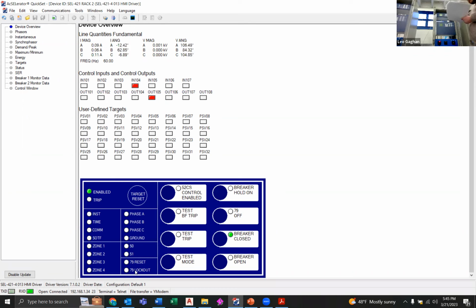So what we're going to expect to see is a test trip, and then 5-second open interval, a reclose. I'll then do another test trip to a 10-second open interval. It'll reclose, do another test trip, go through a 15-second open interval. It'll reclose, and then I'll do a last test trip, and then it will drive itself to lockout. Because it's tried as many times as it can, and it's determined that it's a permanent fault.